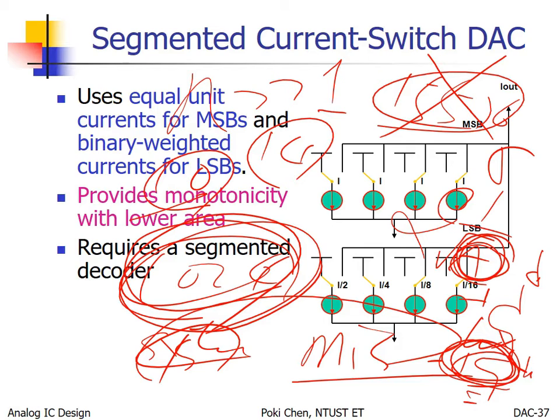Monte Carlo simulation only handles the random mismatch. It has no idea about systematic mismatch. It means after you run the Monte Carlo simulation and achieve a good enough result, don't be too happy, because you still need to pay attention to good layout pattern. Otherwise, the output after fabrication will still be very bad.